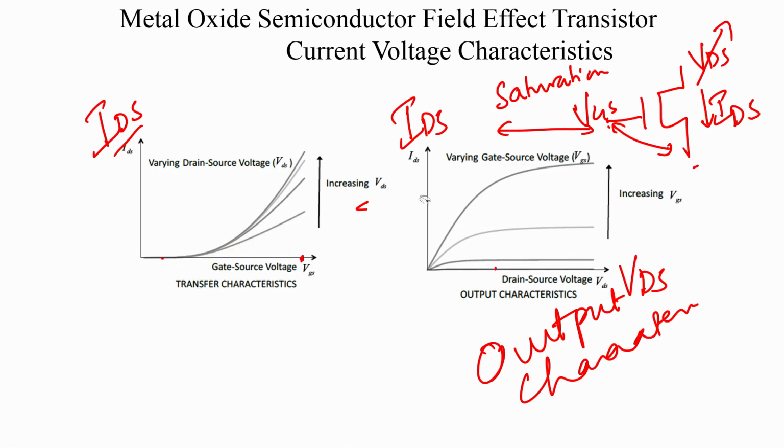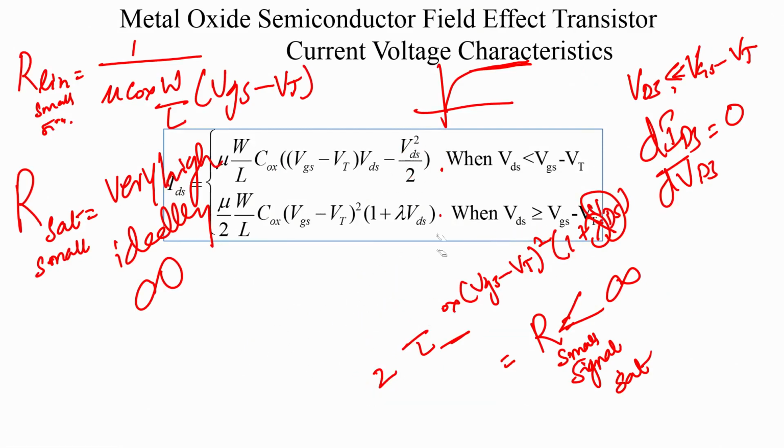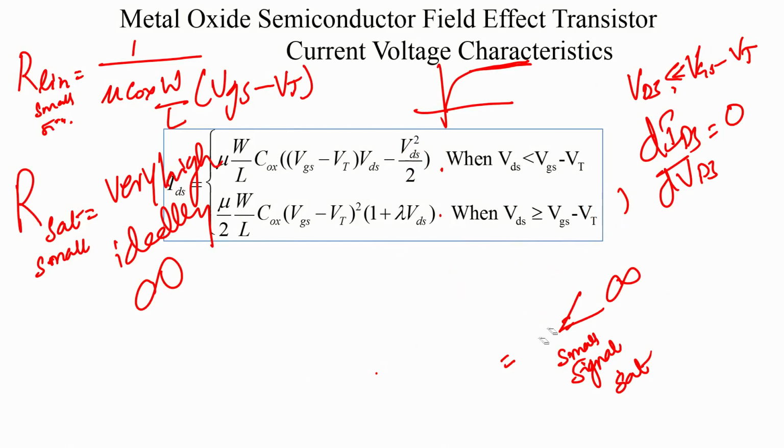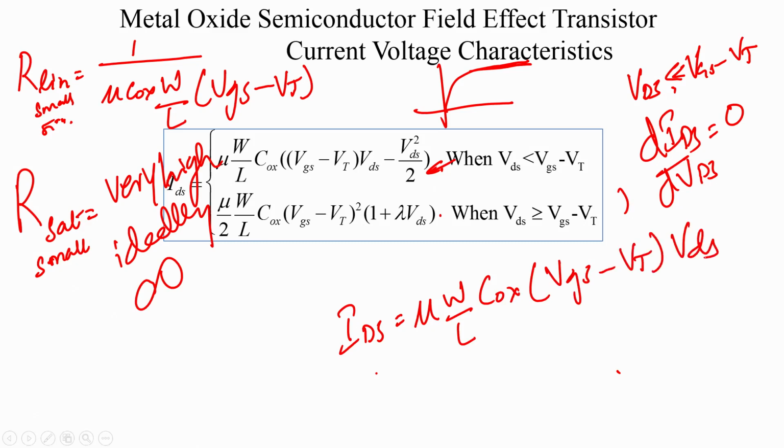We will have a small module on parameter extraction where we can show how to use these characteristics to extract the parameters. But just to look at that point again, let us take the linear mode operation of the MOSFET. So, here is the MOSFET in linear mode. We will say it is deep linear where VDS is much smaller than VGS. So, IDS is mu Cox W over L into VGS minus Vt into VDS. Now we are plotting the transfer characteristics. How does IDS depend on VGS?